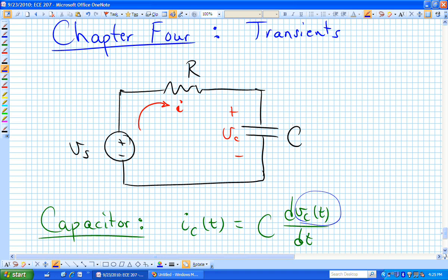What do you know about the energy storage elements in this circuit? Which of these elements can store energy? The capacitor. And there's only one capacitor or a capacitor equivalent. You could have had two capacitors in parallel, two capacitors in series, and now you've combined them. You effectively have one capacitor. With that one energy storage device, you're now looking at a first-order differential equation.